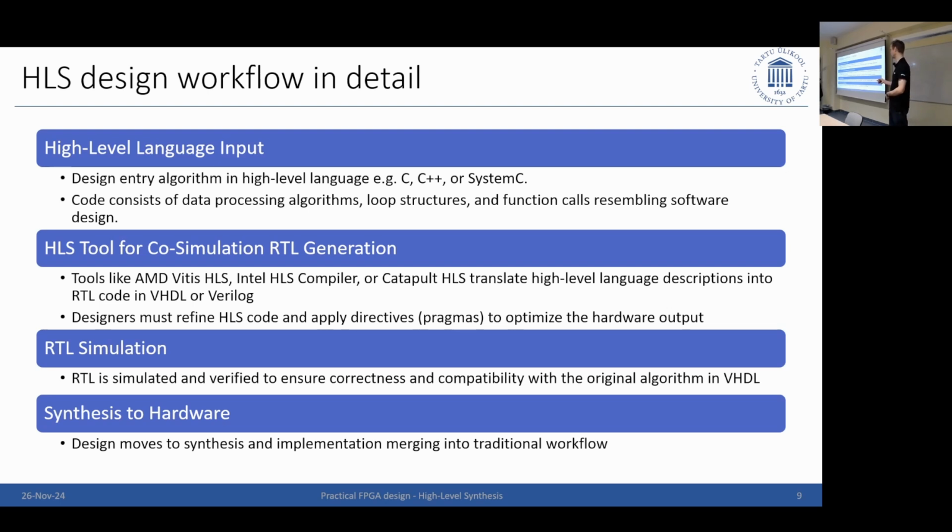And you see already here the workflow is a bit different. In VHDL, if you remember, there's much more architecture things. So you care about which interfaces I use, how they connect to each other. This all, besides functions and function calls and return values as you have in C, C++, is not going to be a thing anymore, which is good and bad at the same time, right? Like you don't have to take care of all this interfacing and this hierarchy, but you cannot. So you lose the benefit of that as well.